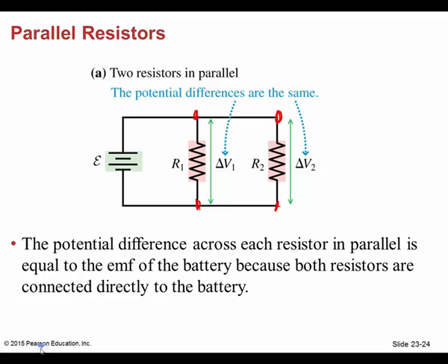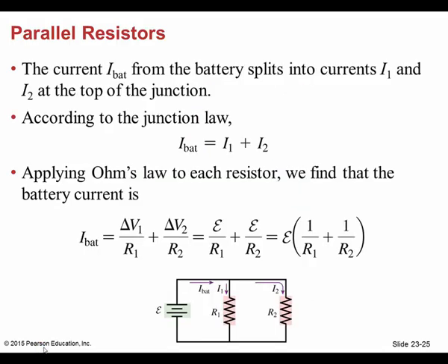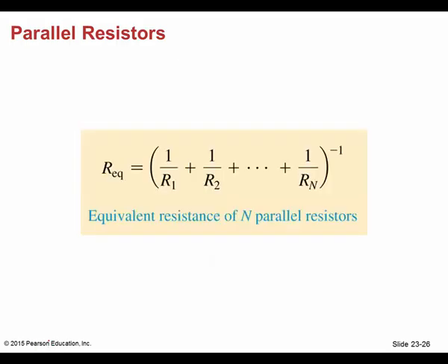One thing you need to try to remember is that the current in a parallel resistor splits. So notice how the current and the voltage from series to parallel flip-flop. Series circuits, the current is the same in all resistors, but the voltage divides according to how much resistance you have on each resistor. Parallel combinations, the voltage is the same across each resistor, but the current divides. And that's what they're telling us here.